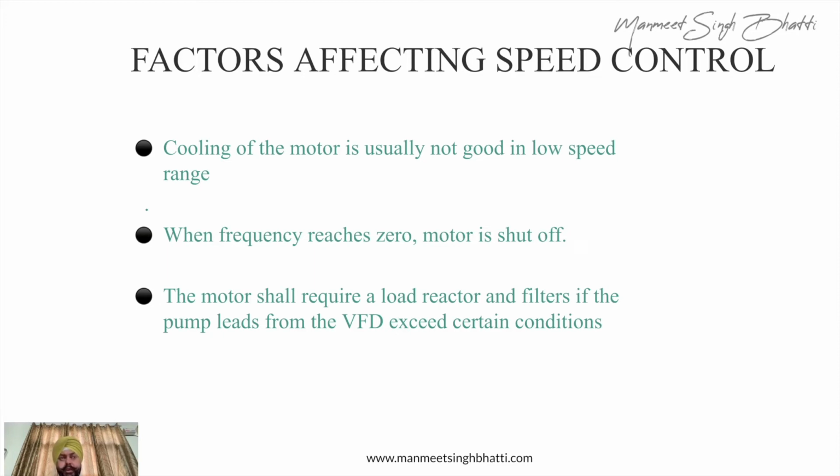So you have to be very careful that wherever you are going to use these VFDs, you should have proper ventilation. Or in case the VFD speeds are going very low, like around 20% or 30% of their rated speeds, it's always better to provide an external cooling fan outside that motor so that the motor remains cool.